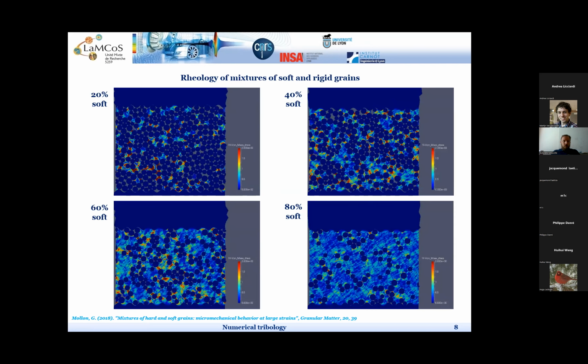To understand this, there are a lot of different devices that are used in rock tribology. We will look at a few of them. So first one which is very useful and very common is the direct shear. It's very useful for slow sliding, and it allowed us to document a lot of interesting data about rate dependence of faults, but only at small sliding velocities.